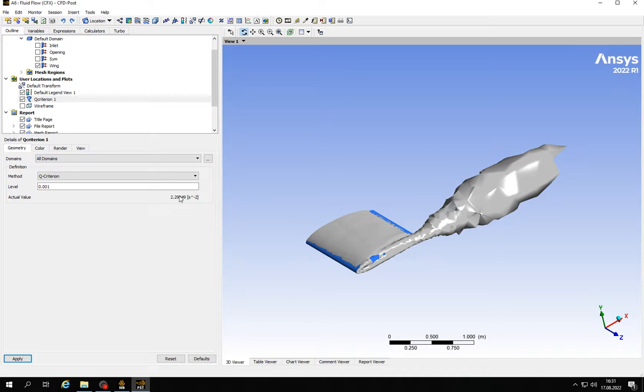The domain you're using is not adapted, so the values that ANSYS is going to give you are not to be trusted. So it's just a matter of playing with the values, but you shouldn't focus too much on what values ANSYS gives you. So you don't really have the actual value, which can be bad for comparison with other configurations.